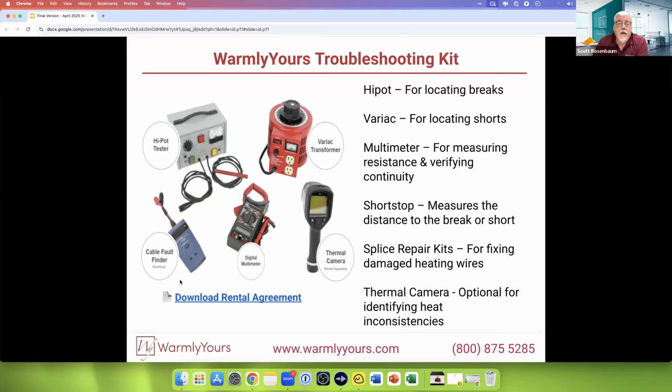And the other thing about this digital multimeter, if you notice this thing at the top, that's a clamp. That clamp helps you know what the amp draw is on a specific product. And that's why you need to get a digital multimeter with an amp clamp on it, because we're going to see why that's so important.